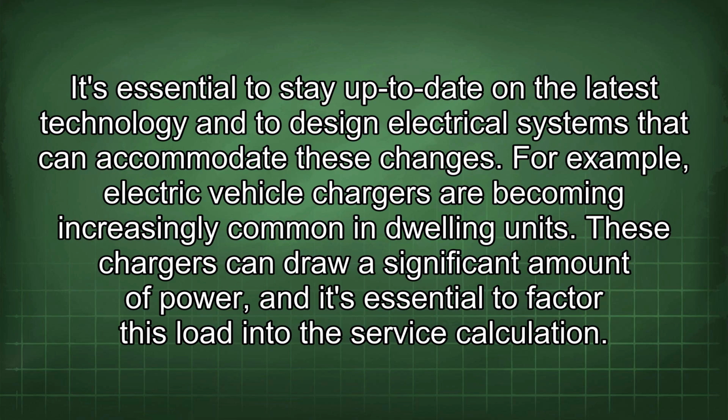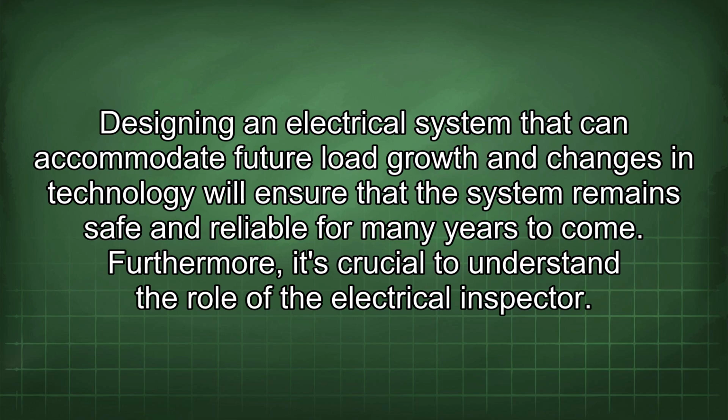For example, electric vehicle chargers are becoming increasingly common in dwelling units. These chargers can draw a significant amount of power, and it's essential to factor this load into the service calculation. Designing an electrical system that can accommodate future load growth and changes in technology will ensure that the system remains safe and reliable for many years to come.